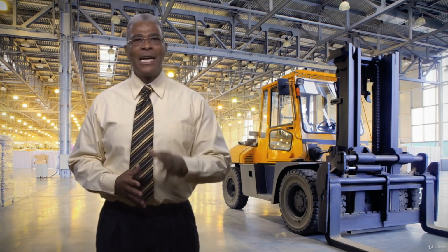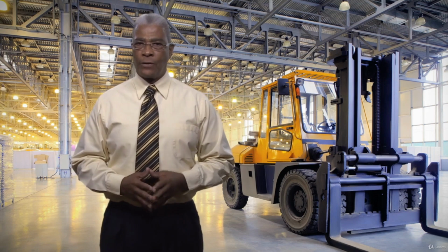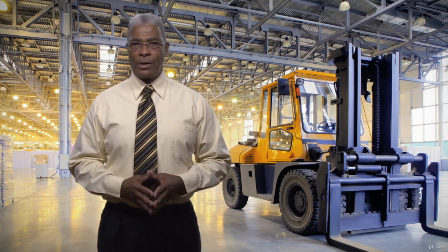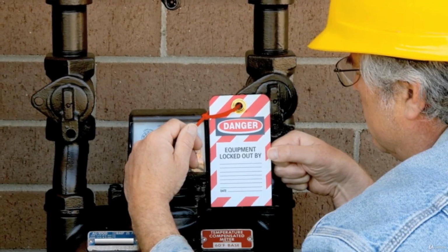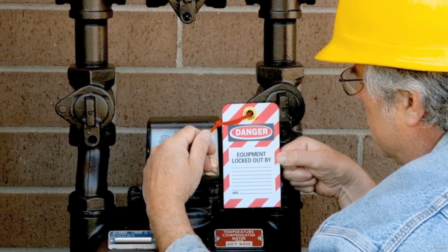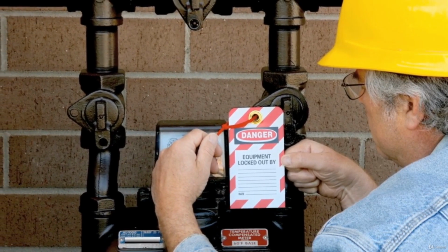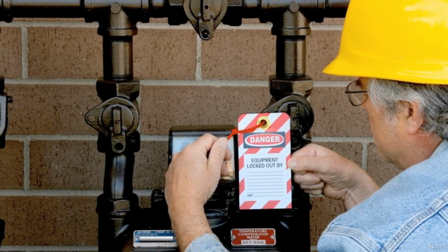Lockout-tagout devices must be individually identified and be the only devices used for controlling energy. Do not use these for other purposes. There are certain specific requirements for locks and tags. Let's review these requirements. Locks and tags must be durable. They must be capable of withstanding environmental conditions for the maximum period of use. They must be constructed and printed so exposure does not cause deterioration of the message on the tag, and tags must not deteriorate when used in a corrosive environment.